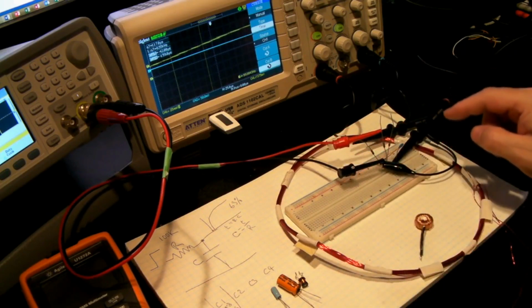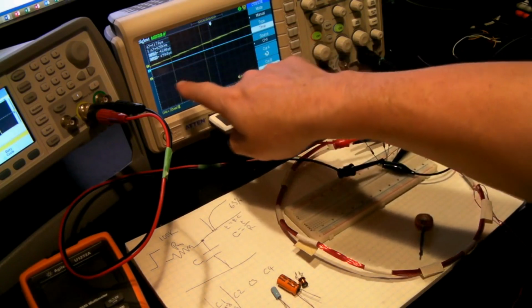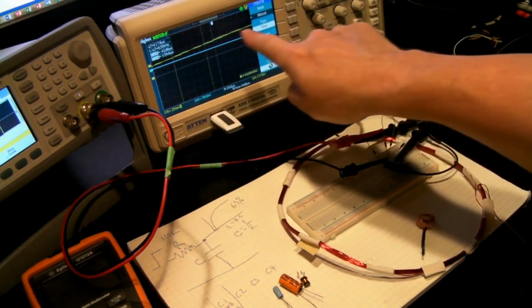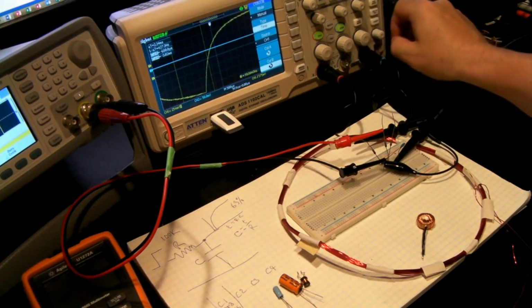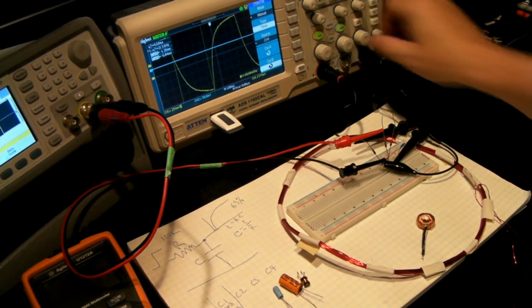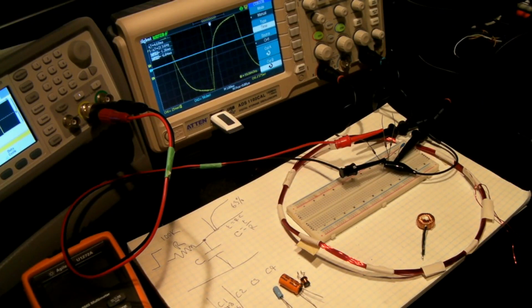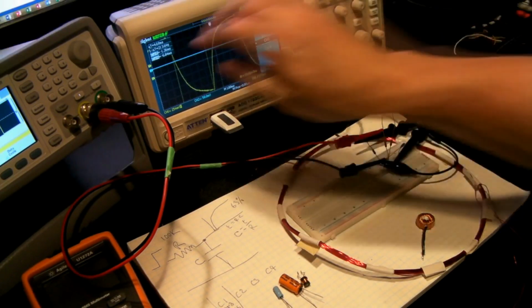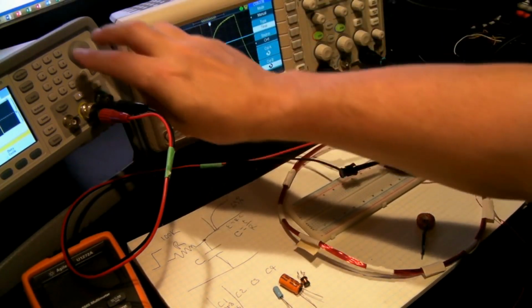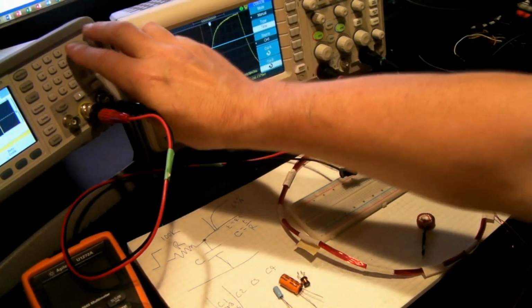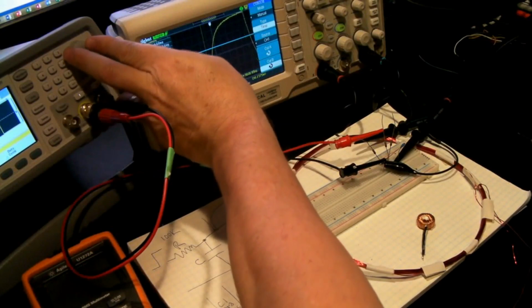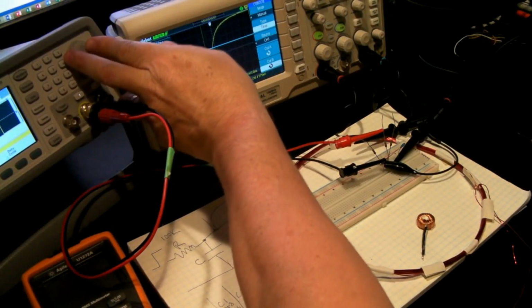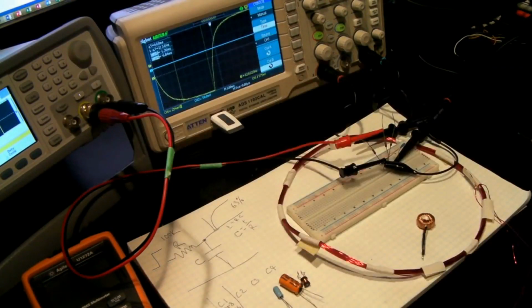Now you can see this capacitor is a lot higher value because right off the bat the oscilloscope trace is much shallower. So if I reduce the time base now, you can see it's again not getting to the flat tops. So what I'm going to do is reduce the frequency a little bit, so that's 90, 80, 70, so about 70 hertz, 60 hertz. Let's just go a bit wider. So that's good.